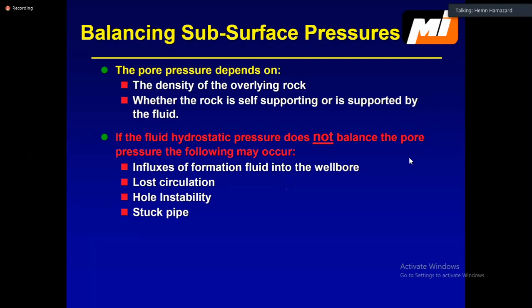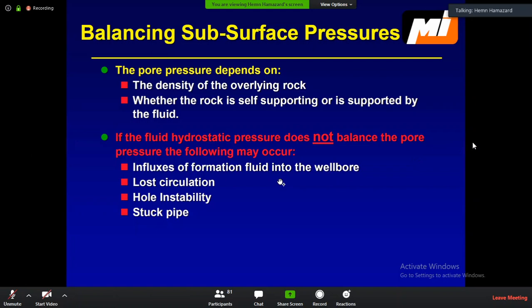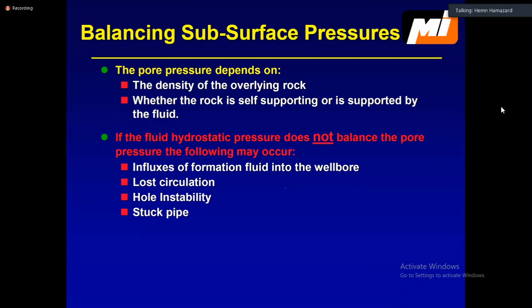The formation pressure is either known if you are in the development phase, or if you are in a wildcat well, you can just assume that everything is connected to the seawater, and then you take the water gradient for your formation pressure calculation. So in this case, your mud must be sufficient and efficient to overcome that trapped pressure or formation pressure, so the kick and well control issue doesn't happen.